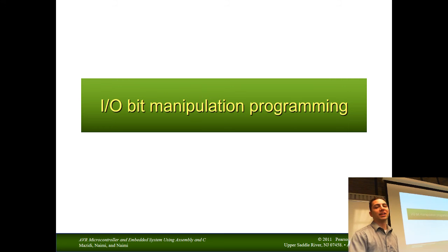I/O bit manipulation. Okay, so there are some special instructions. We're going back into learning new assembly instructions mode after that brief detour. These instructions allow you to manipulate a single bit, not a whole byte at a time, but a single bit inside of an I/O register. This only applies to I/O registers.